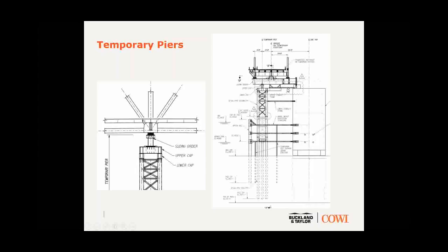And really the reason for those is we did not want this tower to be completely disconnected from the permanent structure while we were undertaking these tricky lifting operations of these huge spans. So the purpose of the two stability frames is to maintain a connection between the temporary tower and the permanent concrete pier at all times. And the reason there's two of them is we have to lift the truss through, close a second connection, and open up another one, and I'll show that a bit more later.